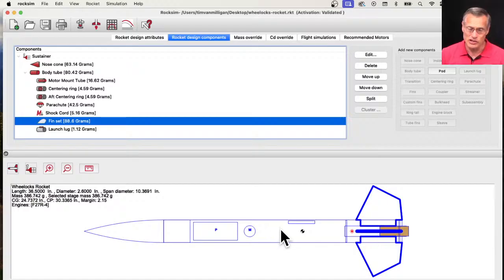So when you're losing oxidizer from in front of the center of gravity, the center of gravity is actually going to shift backwards as it burns. So with hybrid motors, that's where you might want to think about having a center of gravity shift in the rocket motor file.